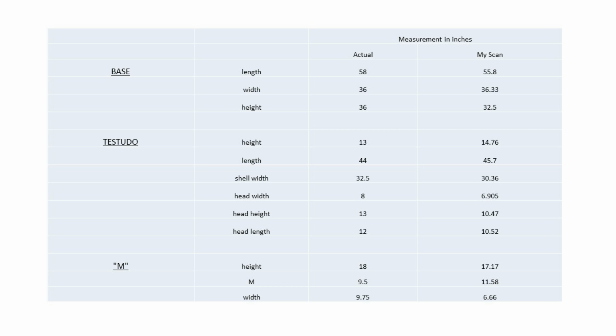So I went out and used a tape measure to get each of Testudo's measurements, and we can see here comparing it to the actual scan I got using just the point distances in MATLAB. We can see they're all pretty reasonable. For example, the length calculation is at less than 4% error difference, so I think that's still pretty reasonable.